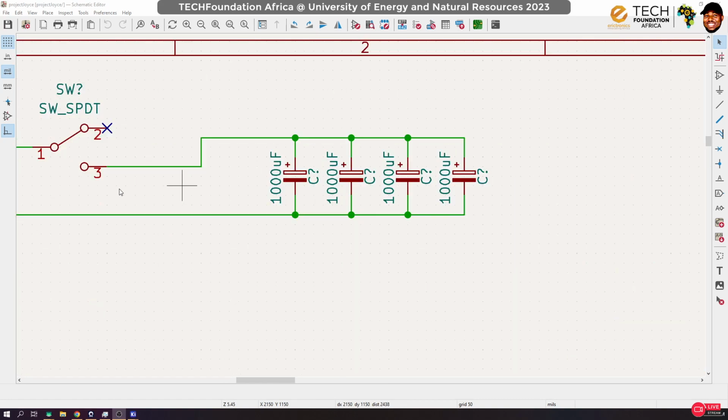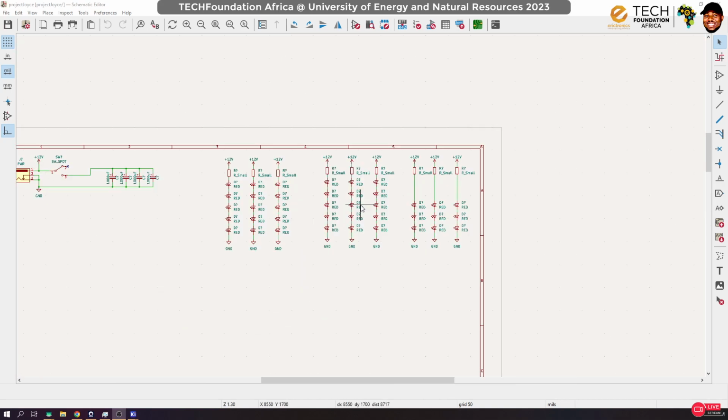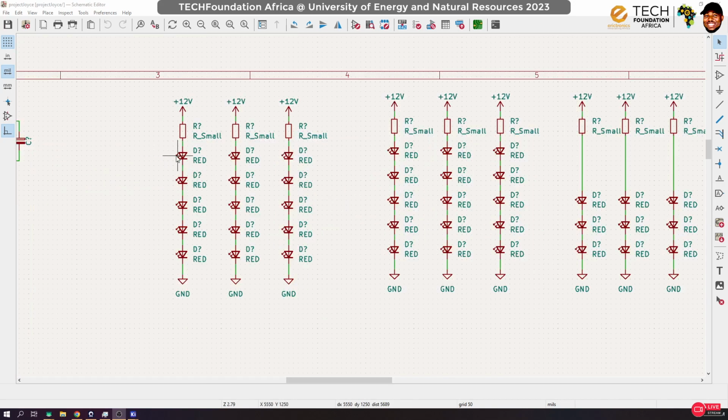Okay, so in here we are using their circuit symbols instead of the actual pictures, and then we have strings of LEDs. Now, I said yesterday that we are going to use a power source that is 12 volt. Okay, our power source is 12 volt, and to judiciously use the energy, not be wasteful, we are serializing the red LEDs, we are putting them in series.